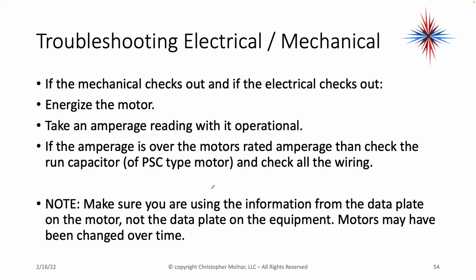Again, be careful with your electrical troubleshooting. Sometimes when you're taking voltage readings, you're working on energized equipment. Your hands are in high voltage. When you're taking resistance readings, protect your meters and isolate the components. Make sure the voltage is turned off. Don't just trust the disconnect or switch. Actually check and make sure the voltage is off.